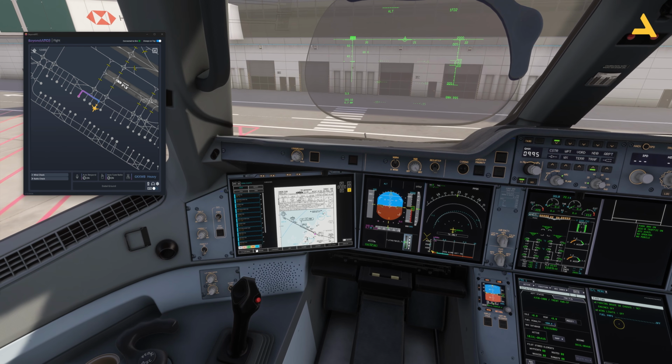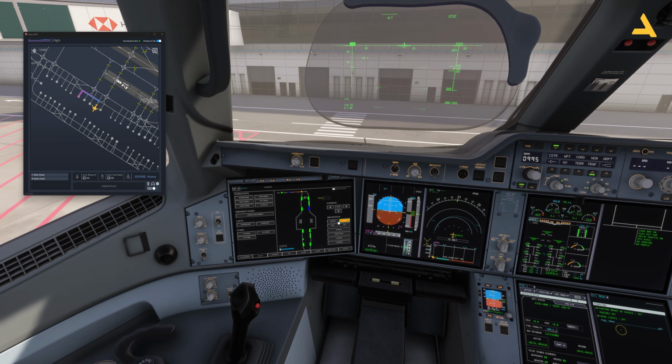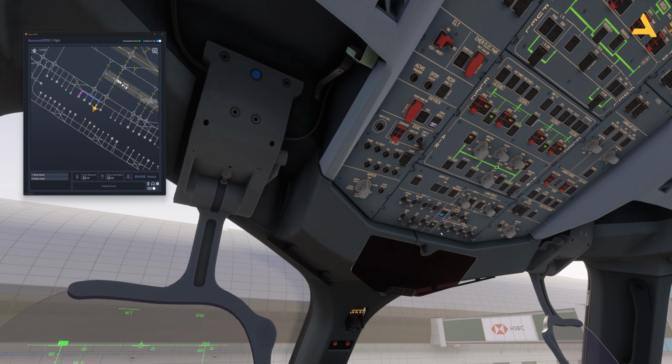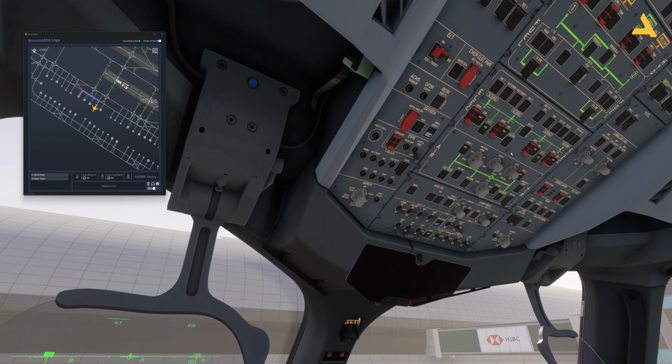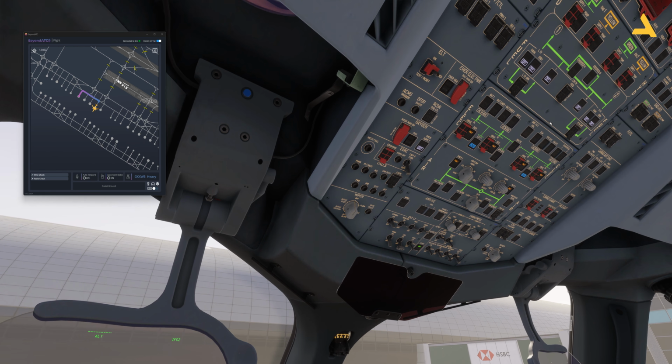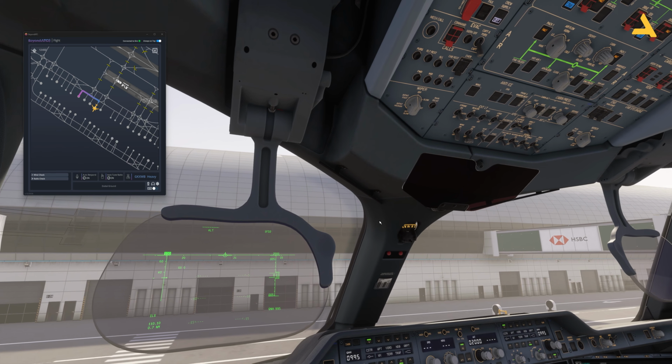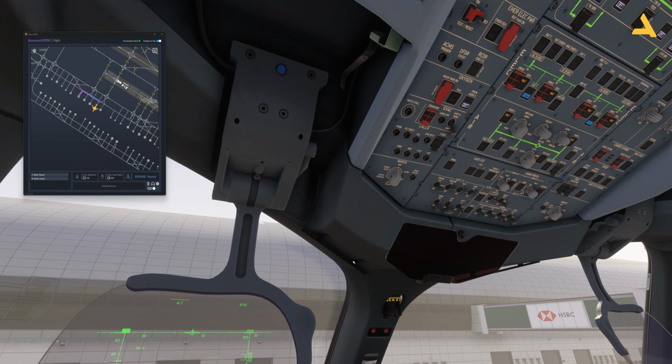I can connect the ground power unit and apply the chocks, and let's get the air conditioning as well. And now you can see external power is available. So let's switch to external power, turn off the APU, and let's turn off the fuel pumps. That's it. Beacon not required. Nav lights can be on. Logo lights can be on. Oh, seatbelt signs are now off. That's it.